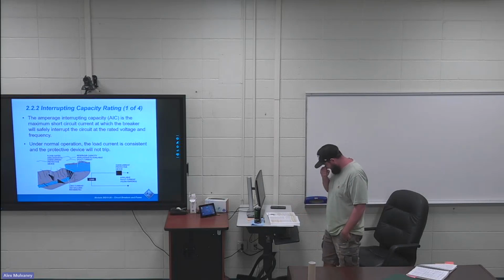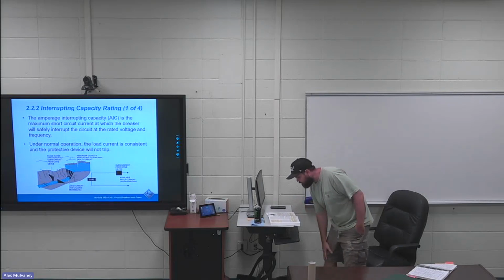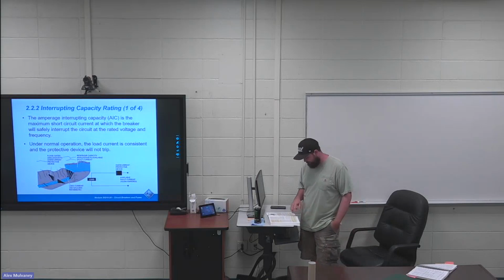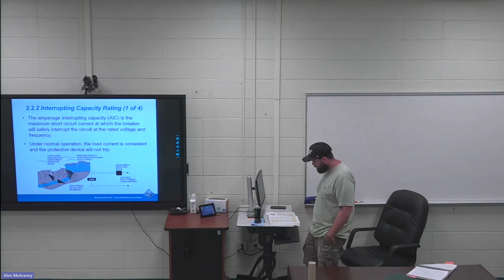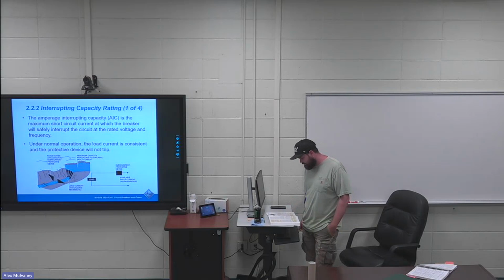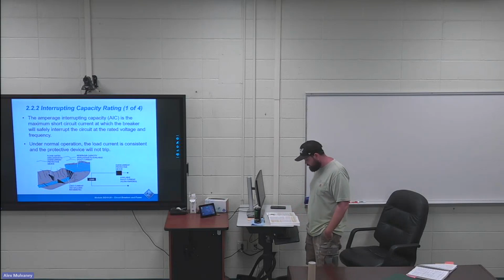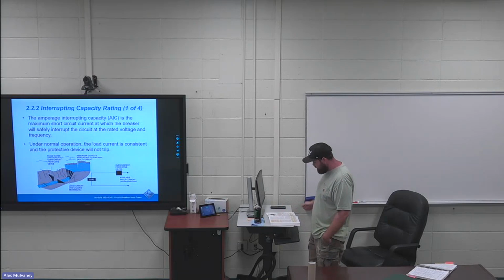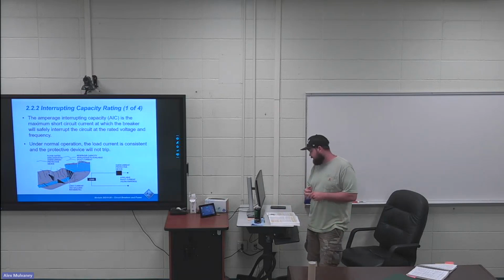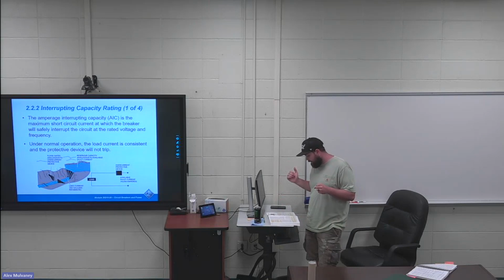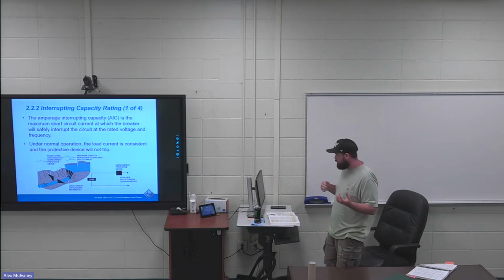Page 10, a lot of highlights on page 10. First paragraph, first 2 sentences are highlighted on page 10. There are circuit breakers available for almost every need in any electrical system. For example, in circuits where the circuit breaker must be highly sensitive to amperage changes, in an environment where the temperature changes are great, the ambient compensating circuit breaker may be used. So that's temperature changes a lot with electricity. So you can have a circuit breaker that makes changes based on the temperature, because at certain temperatures they should trip sooner or later than others.